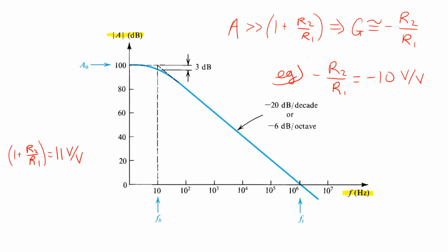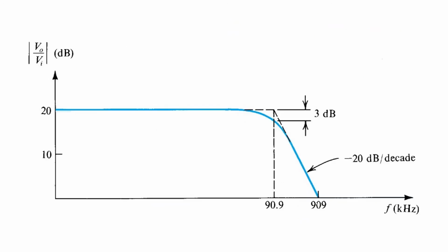That's slightly more than 20 dB. So essentially, the inverting configuration would behave ideally up to around frequencies where its gain dips below this value. From the plot on the preceding page, we see that that happens at around 90 kilohertz.